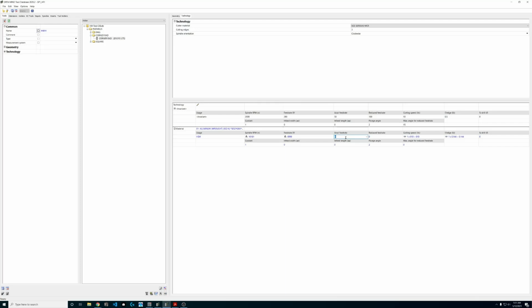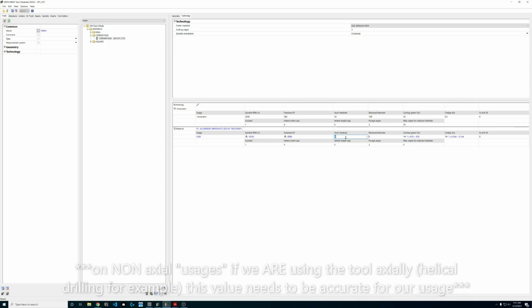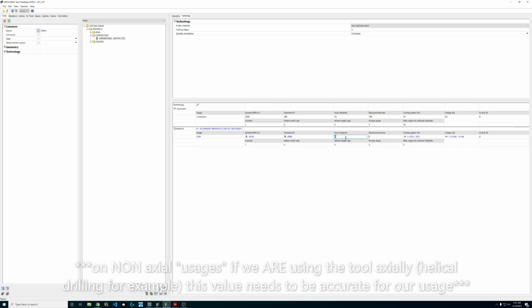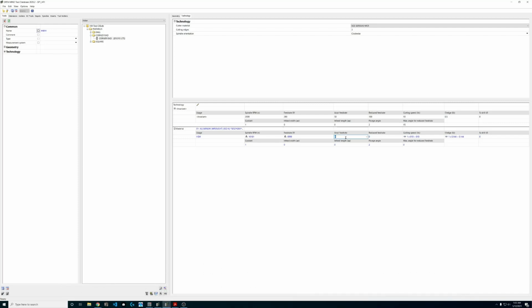if it's not in a part where you can easily spiral down or something and that tool's coming away from the workpiece a lot, everyone's seen a machine where you're ball end milling on a 3D surface and it goes into the cut and it cuts across and it comes up really slow and it goes back over G0 and it comes back and it feeds in so slow. Then it cuts across and it goes up again, G0, and then it feeds and it seems like it takes forever.